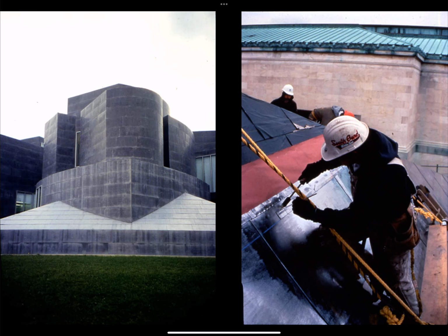So we talked in the previous lecture on roofs about seamed metal roofing systems, and the seamed metal roofing and wall system of this building, in which we saw that two pans of metal are brought together with a cleat in the middle, and then those elements are folded over several times. So the folding produces the interlocking joint.